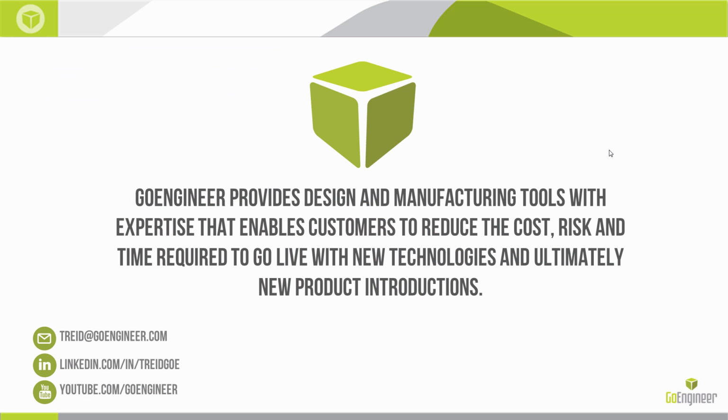Okay, so with that, that's the intro into 4-axis machining inside CAMWorks. The big takeaways here are you have indexing, you have wrap features, or you have simultaneous features. Those step up progressively in complexity, but also functionality. A lot of parts that you cut are going to be a combination of those. They're going to be 2.5 axis, maybe 3 axis, plus indexing, like the pump housing.